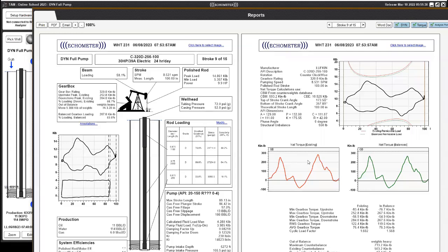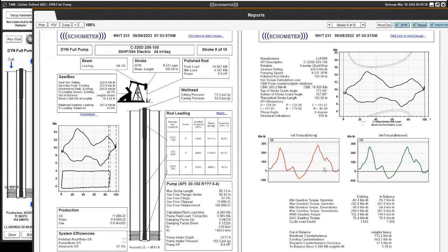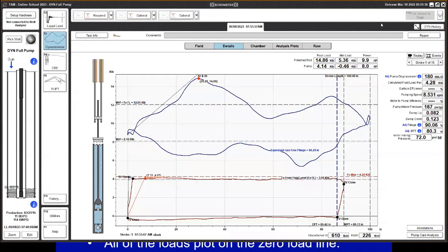There is a gearbox existing, so this is just a little bit heavy weight. So that's way heavy here, but still not overloading the gearbox torque. So that's part of the interpretation of the gearbox. If you want to balance this pumping unit, really it's only having to move 3 inches. It's not gonna gain a lot on that. So maybe for 3 inches, you don't want to spend the time and the money on the crew to go and balance that pumping unit yet until the condition changes.